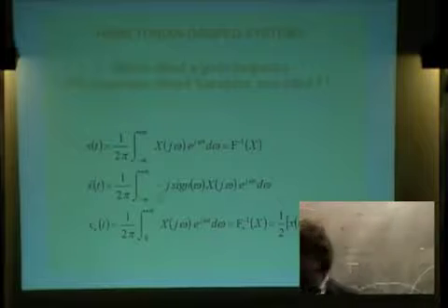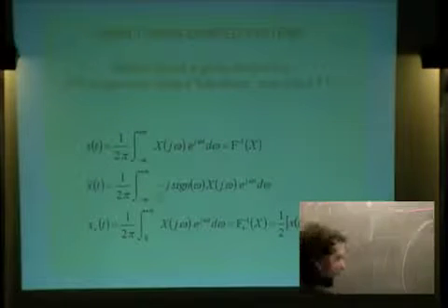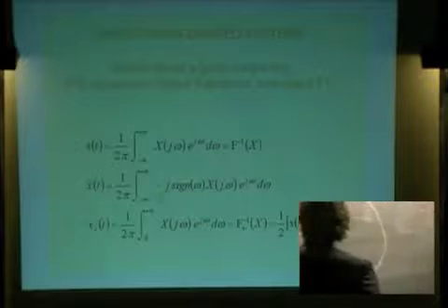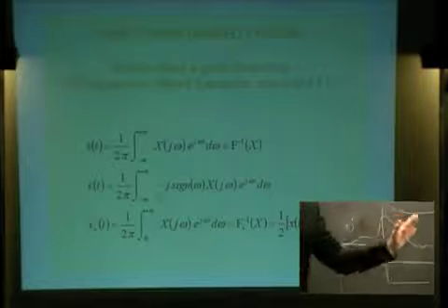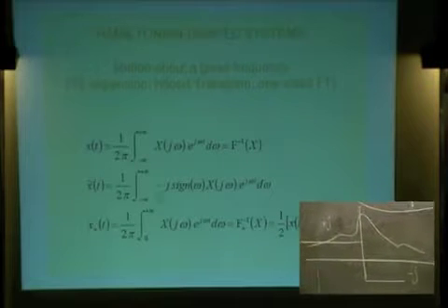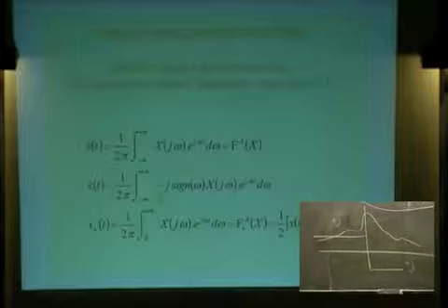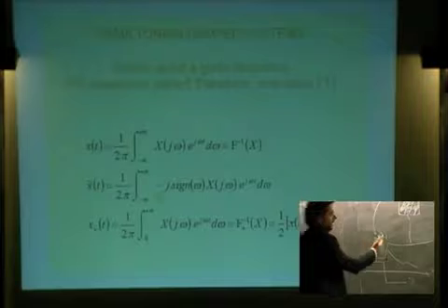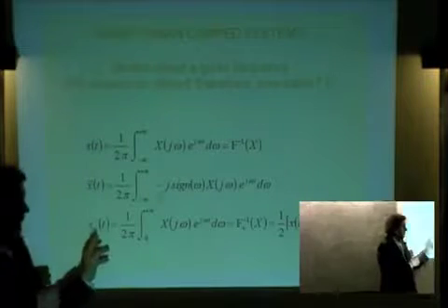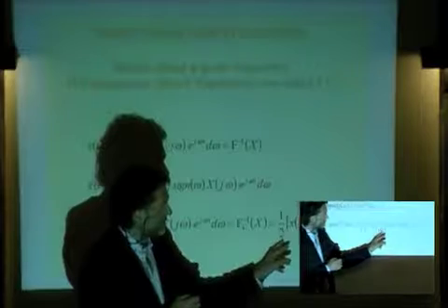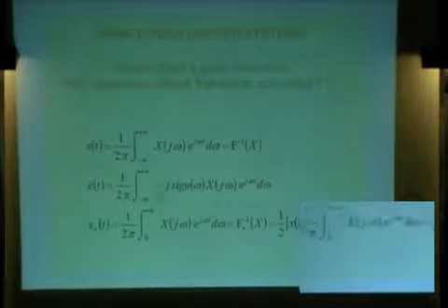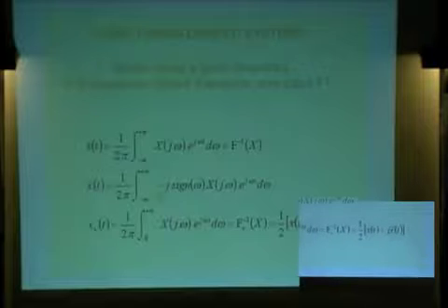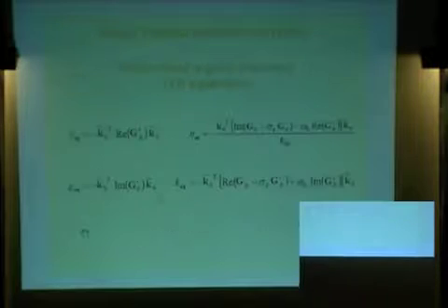You take the Fourier transform of your signal, then you erase half of it, and then you transform back to the time domain. Then you obtain the so-called analytic signal. By simple combination, one sees that it is one half of the sum of a complex signal that has the real part x and the imaginary part the Hilbert transform of our signal. This is useful for what we are doing now.